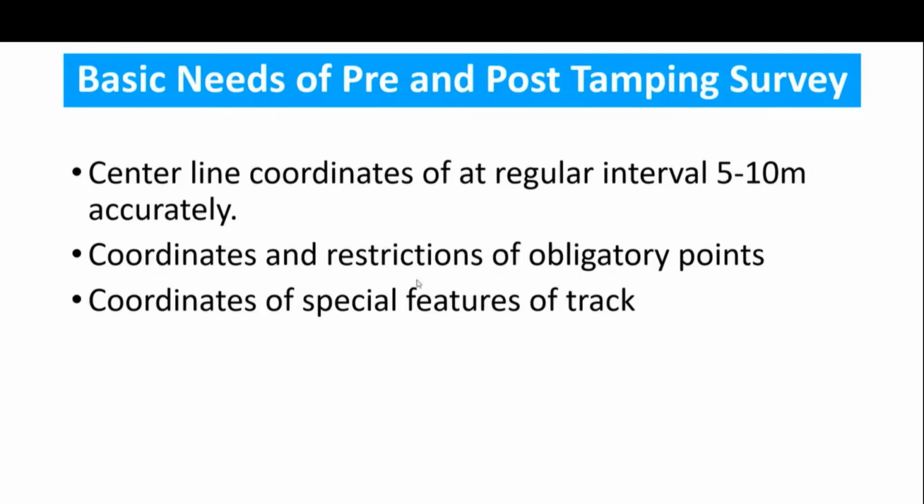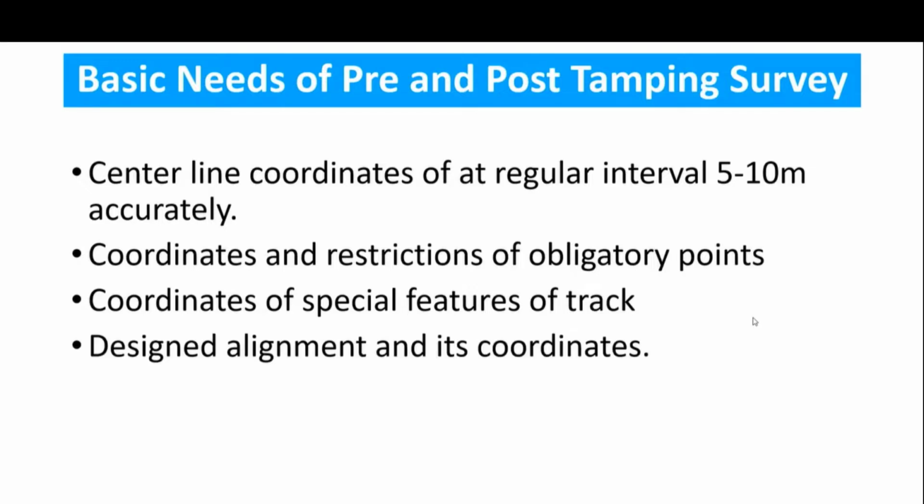Then also the special features like gradient, start of curve, end of curve, where the vertical curves are there, they also have to be picked up. Then super elevation, degree of curve, everything has to be picked up during the survey. Then we determine the design alignment.